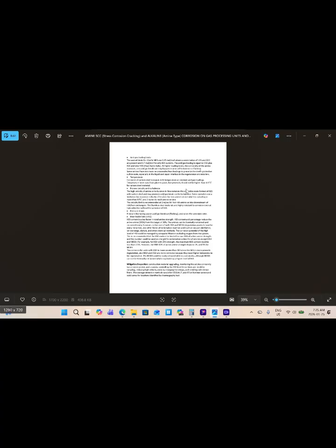Process velocity and turbulence are very important. The high velocity of the amine and turbulence in flow remove the protective scale of H2S on the carbon steel. So we need to avoid turbulence in the flow pattern. Normally there is a number of 6 meters per second for velocity in the amine system, and amine service operating at more than 93 C is not supposed to exceed 2 meters per second velocity.